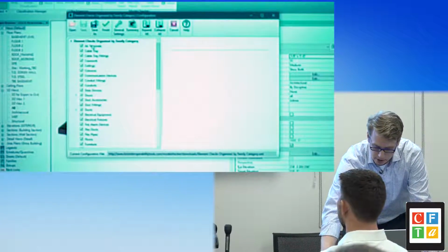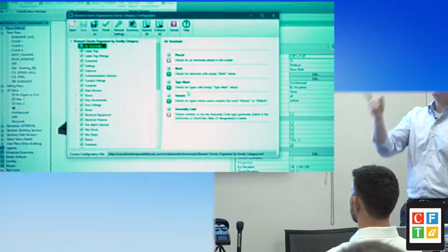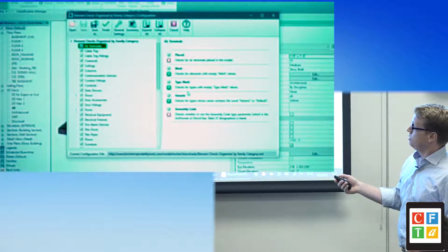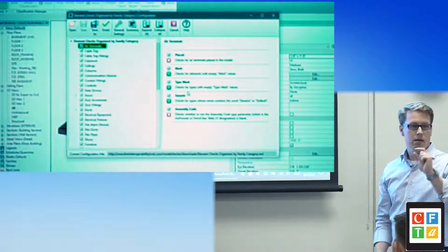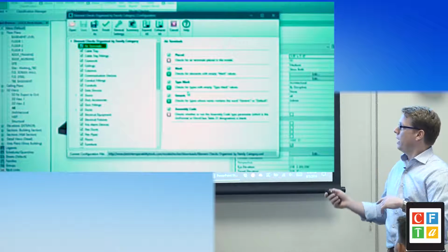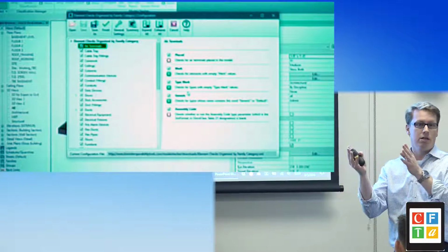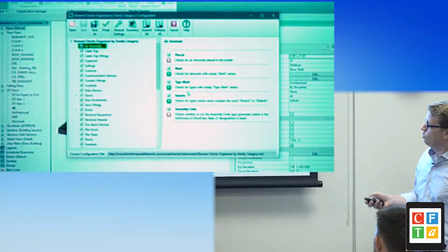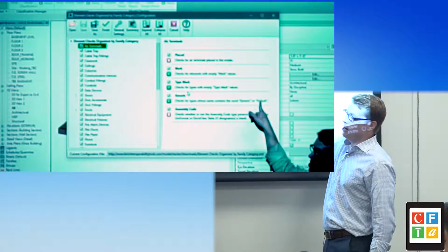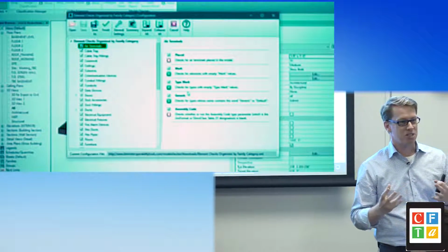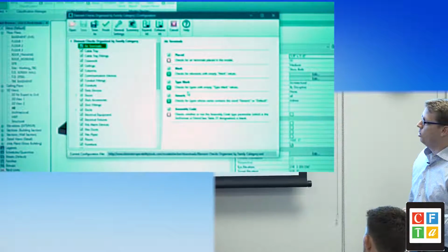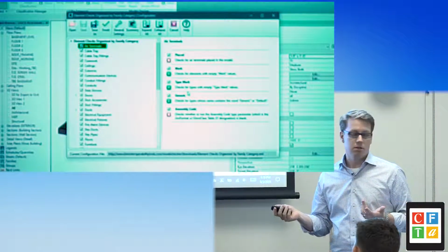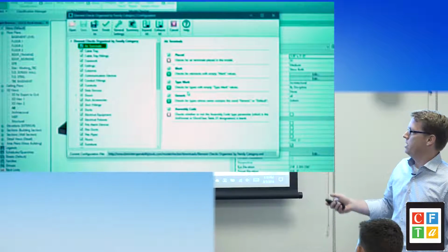And then I can go look at what it's looking for. So air terminals, right? Ceiling diffusers, things like that. What's it looking for? It's looking to see that they were actually modeled. It's looking to see that they each have their own unique identifier. That's the mark. And a type identifier. So all ceiling diffusers of the same type have an identifier as well. Something I can track. It looks to see that somebody didn't put some in that had the word generic or default in the name, that it's actually something specific. And then assembly code generally is the OmniClass number, the Uniformat number assigned to it. So these are just some of the examples you can get.